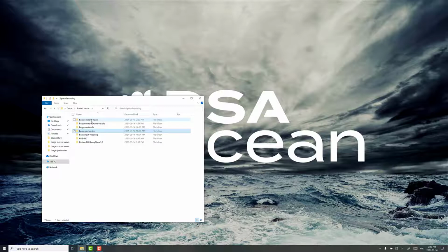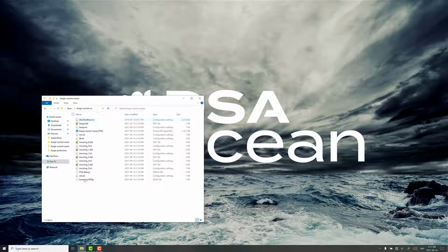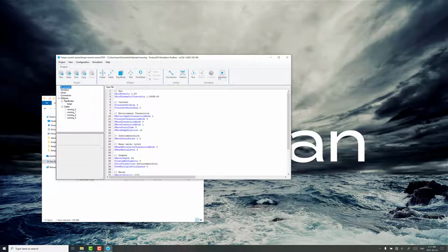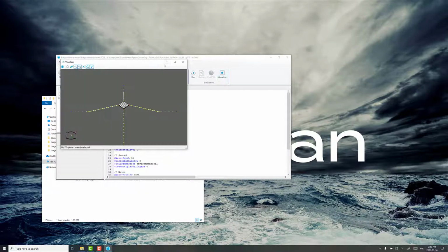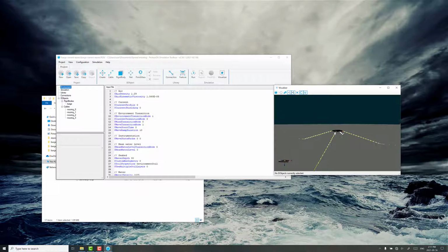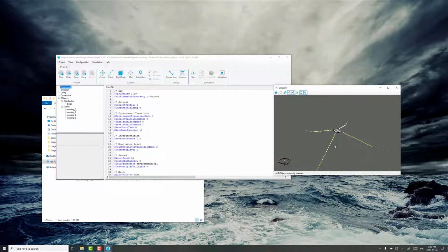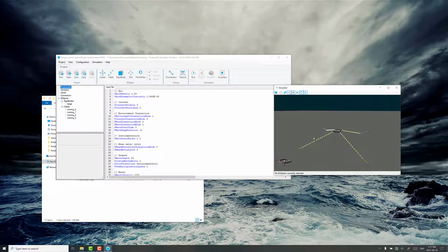And now we've set that up as a starting condition for an environmental load case, and we're going to take a closer look at this. Set up now and set up the environmental conditions. So here's our barge. We've already gone through the process of pre-tensioning the lines. It's ready to go to set up an environmental load case. And what's an environmental load case? We just mean some combination of wind, waves, and currents that we can check the loads in the mooring and make sure the components are the right strength, or maybe we need to make an adjustment to the mooring configuration.